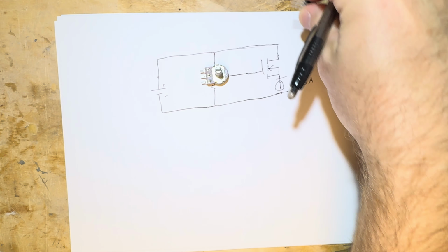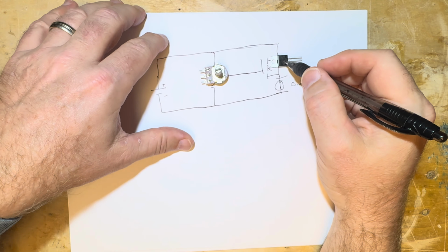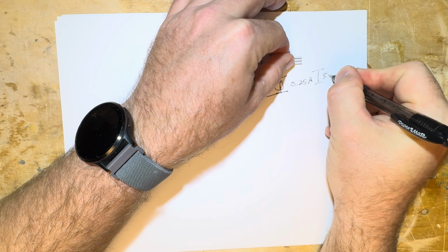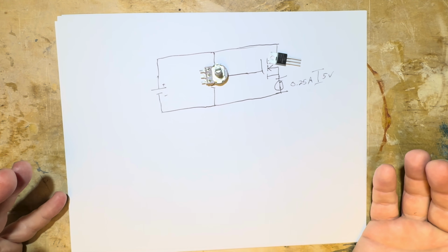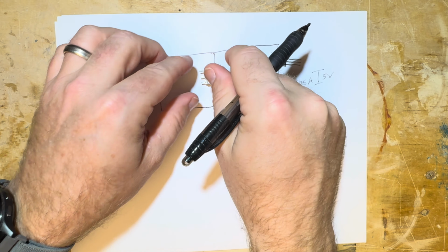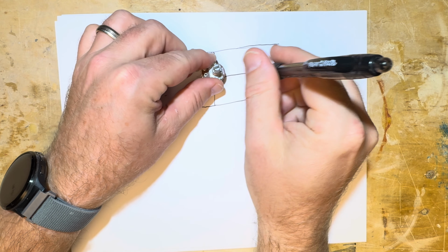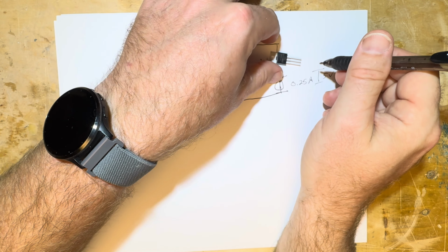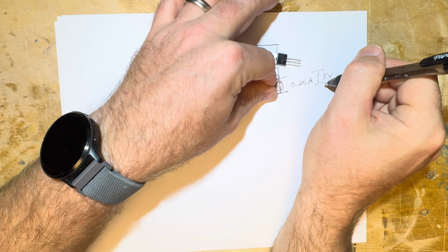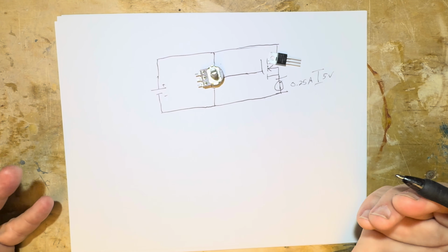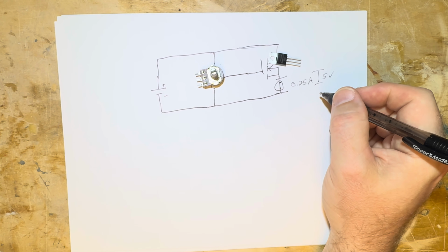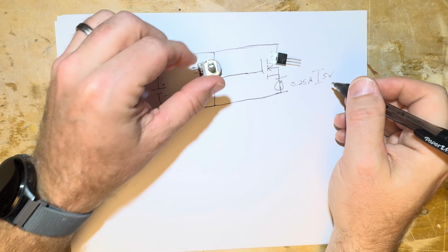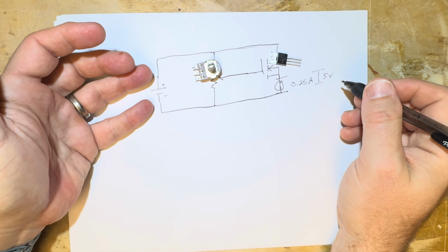And we saw, there's our MOSFET. We can dial in a particular voltage drop across our MOSFET to target our 5-volt voltage drop across our load here. And we hooked this up and it actually worked. It was very, very fiddly. We were able to just dial in the right amount of resistance on this MOSFET in linear mode to get the right voltage drop, about 7 volts, to give us the 5-volt voltage drop across our load, which is exactly what we wanted. Then we saw as we changed the current of our load, the voltage across our load varied dramatically. And you could adjust by adjusting this little potentiometer, but that's a very fiddly way of doing things.